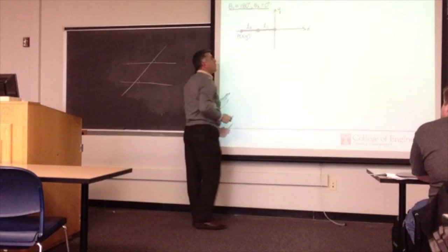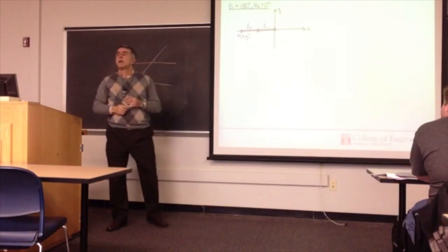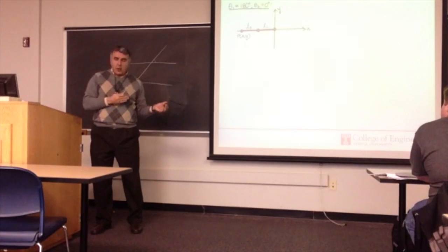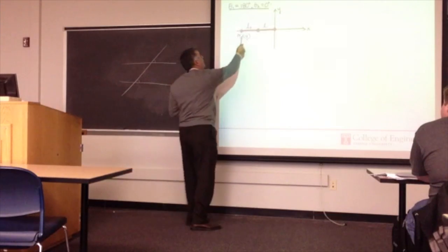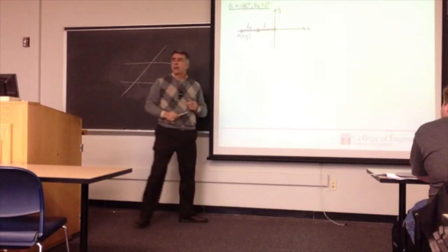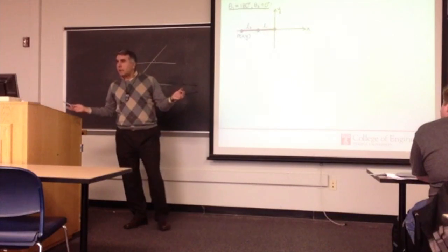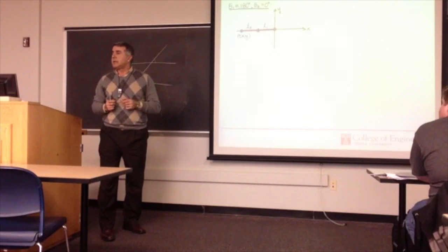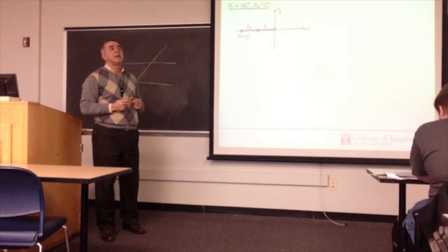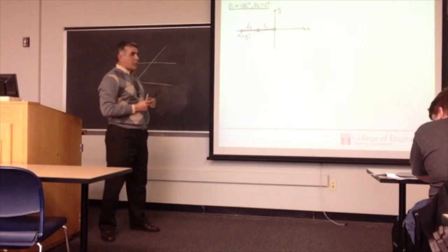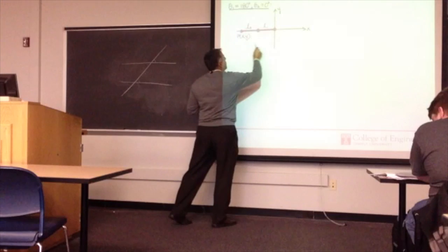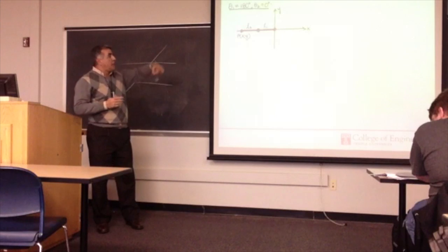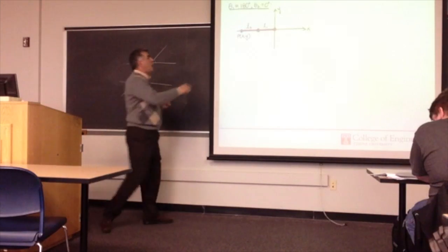But why is theta 2 equal to 0? Because theta 2 is the angle the second link makes with the first link. Therefore, it's 0. That is why theta 2 is equal to 0, and theta 1 is 180 degrees. So L2 would have ended up here. It's a relative angle, one with the other one.